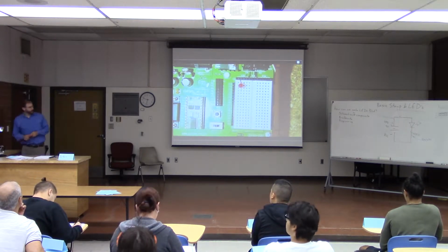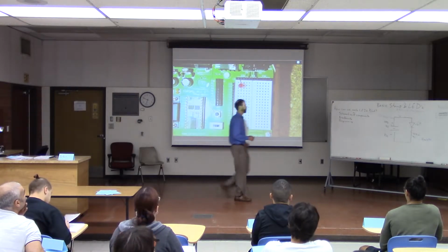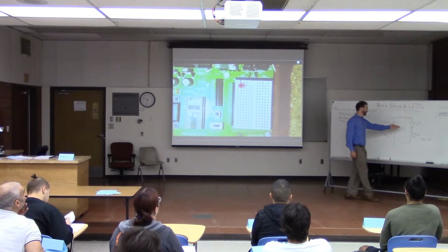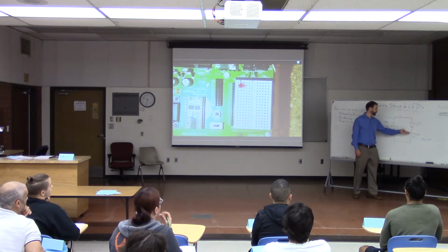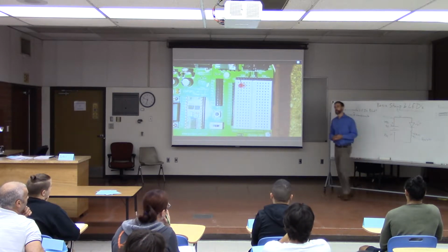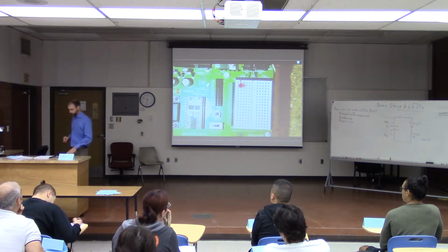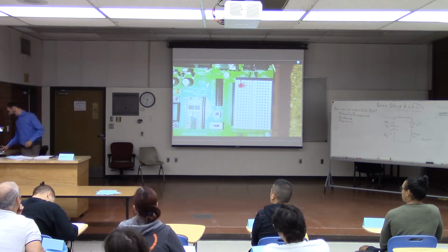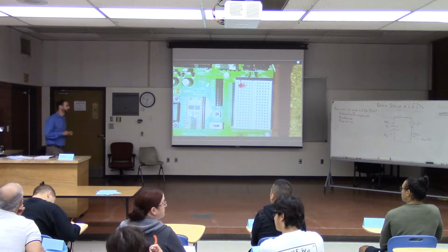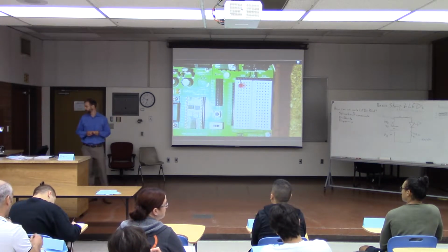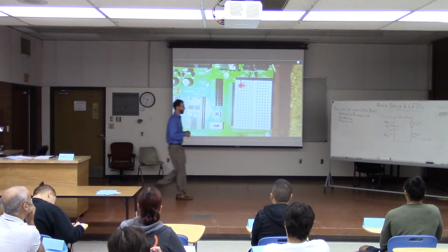Okay. So then we can make our next connection. We see that the cathode of the LED needs to be connected to one side of a 470 ohm resistor. So we said that the way that you can tell what value a resistance is, is by looking at the colors on the resistor.